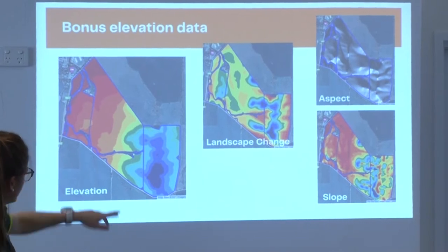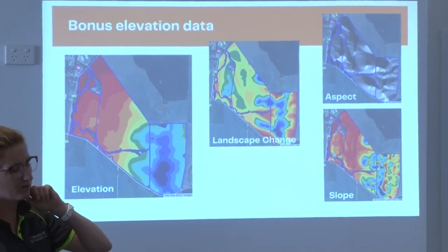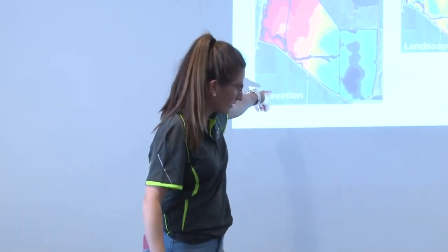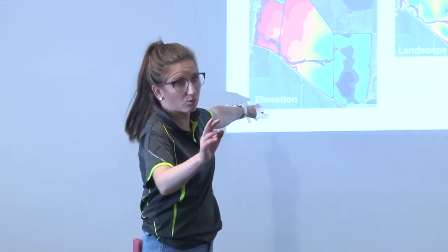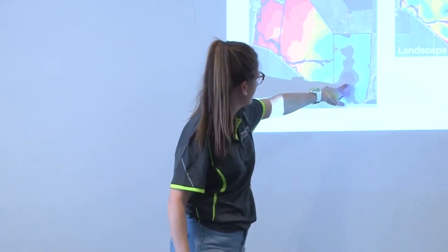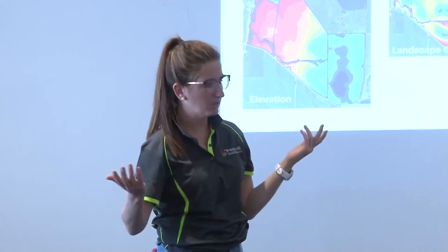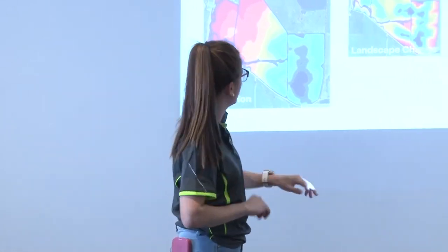It's an elevation map. So we were talking before, an elevation map is something you've probably all got. If you've recorded any sort of data with RTK GPS, this is embedded in yield maps, your seeding maps, anything where you've hit record, this is in there, or you've always collected EM38 data. So that's what you get with the elevation map. This is height above sea level, high and low. And then what I've done after that is pulled out what we call the derivatives. It's still the elevation data, same data, but we can apply what's called a derivative, which is basically another bonus map that you can pull off of the elevation.